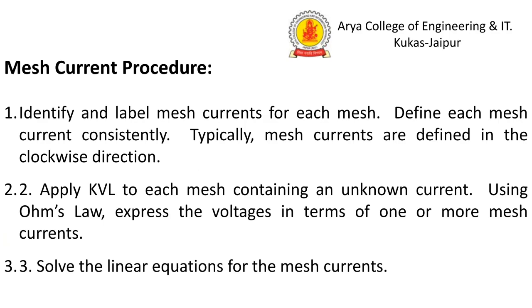Procedure for mesh analysis: identify and label the mesh currents and define each mesh current continuously. Typically mesh currents are defined in a clockwise direction. Apply KVL, solve the linear equations and get the mesh currents.